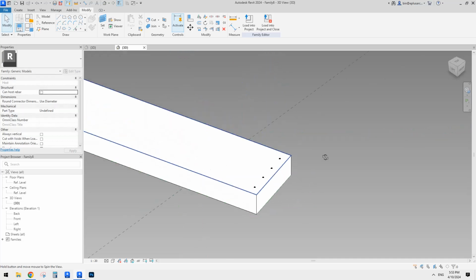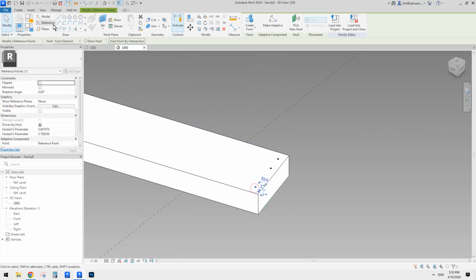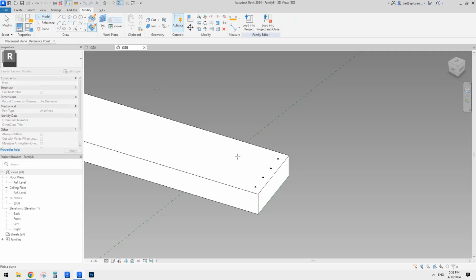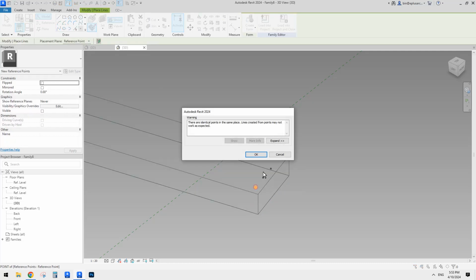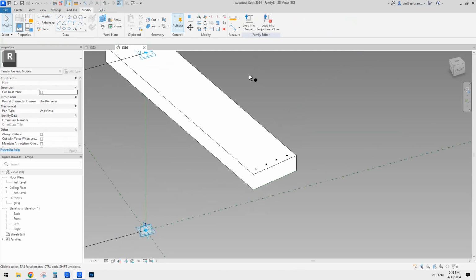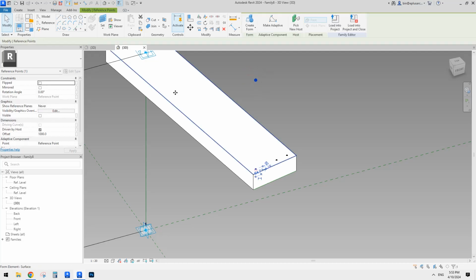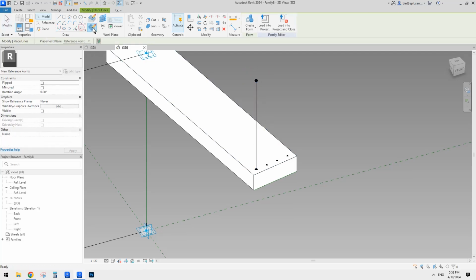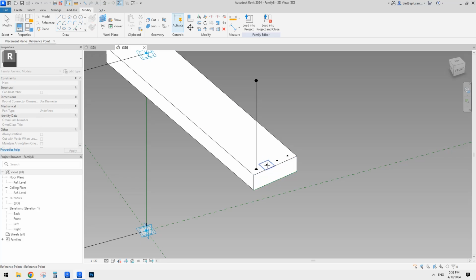Okay, that's all. And then we can just place another point, use draw work plane, set work plane, pick this point, okay, and place onto the point. Click OK, select it, and we can offset it by a number. So for example, 1 meter. So now we have this, and then we can just connect them, create a spline through points. So just quickly do the rest,